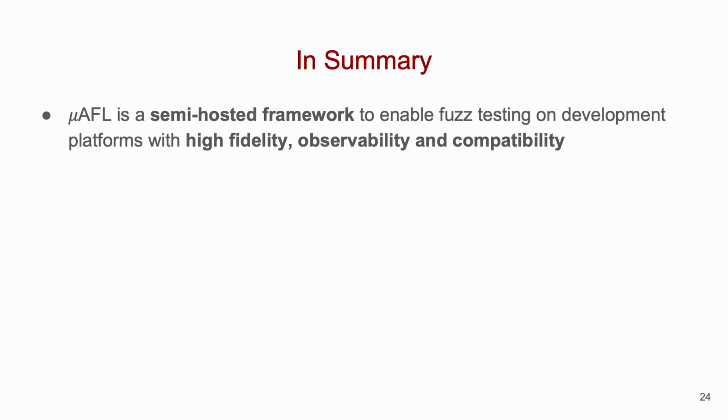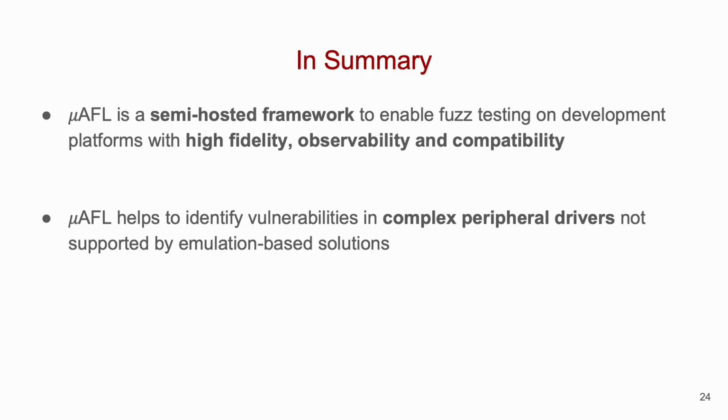In summary, mAFL presents a semi-hosted framework that enables native execution of target binaries on the MCU, achieving high fidelity of hardware, observability of faults, and compatibility with peripherals. This allows mAFL to identify vulnerabilities in complex peripheral drivers not supported by emulation-based solutions.